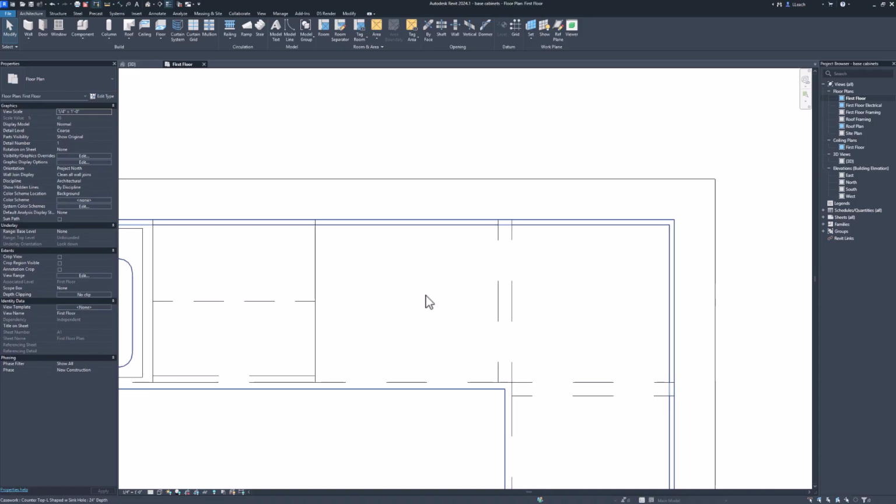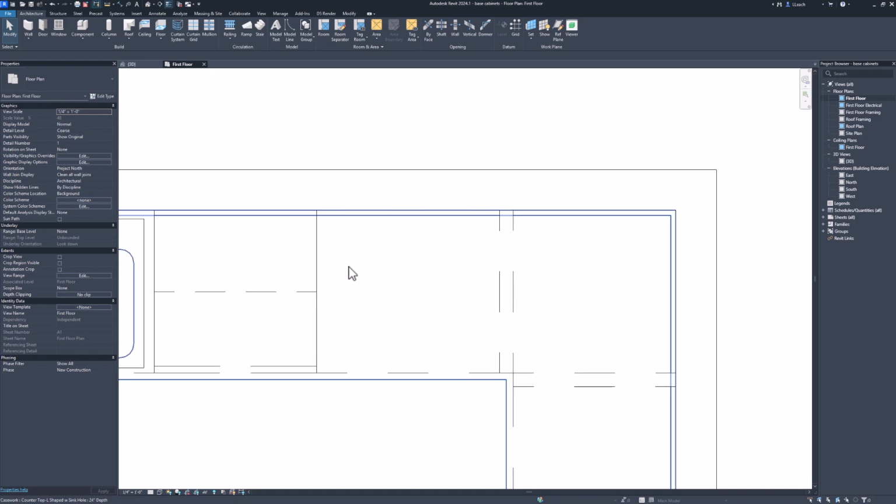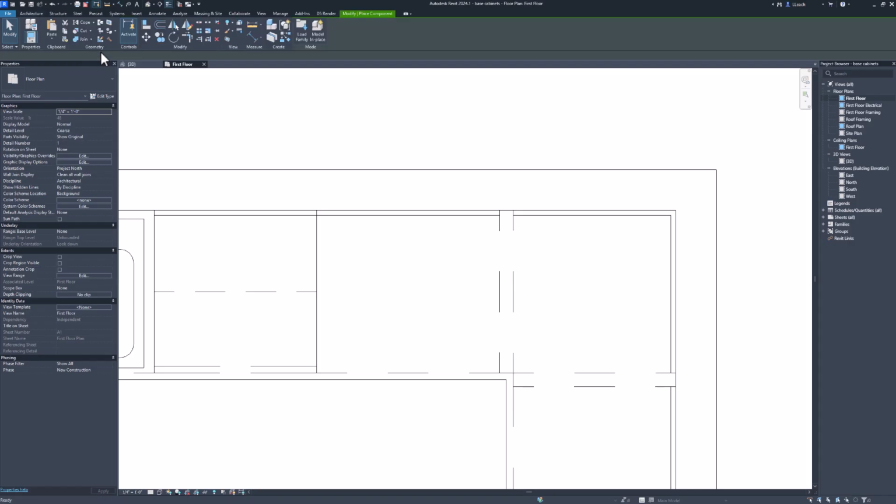All right, so the next one is going to be a little bit tricky because we want to put a 39-inch, since it's not going to match up. Our base cabinets are 24 inches deep. Our upper cabinets are 12 inches deep. So the corner gets kind of tricky. So I'm going to put a 39-inch upper wall cabinet.